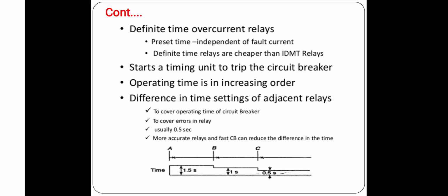If I talk about some drawbacks or limitations of this scheme, unfortunately the operating time is more for faults near the power source. If a fault occurs near the power source, it involves a large current and hence it should be cleared quickly. This is the basic limitation or drawback of this time graded scheme.